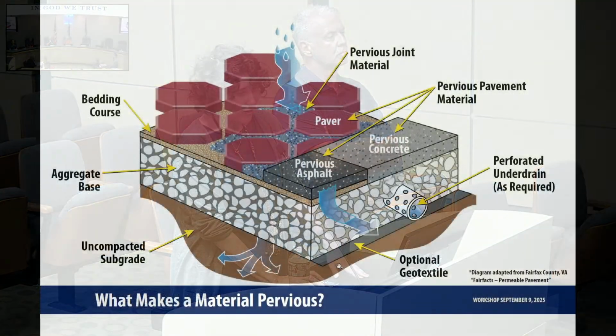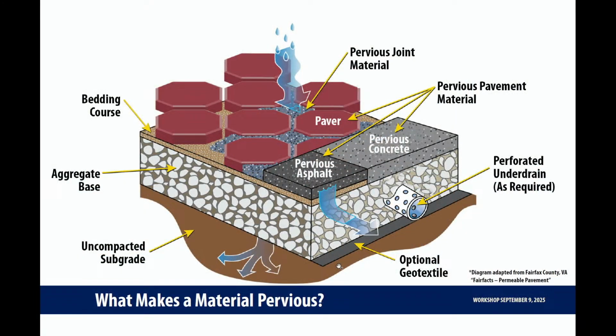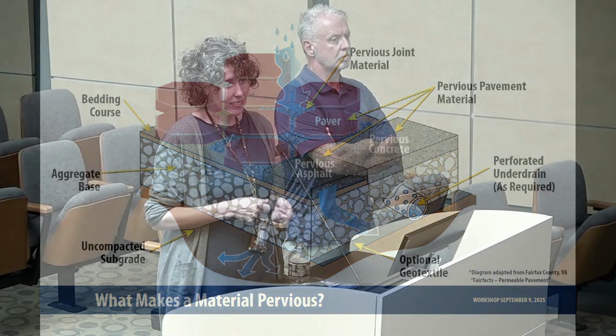Do we have a standard of what's underneath these pavers? All the manufacturers have different standards. There's a variety of cost, and they all look something like this diagram. You'd have a bedding layer for pavers, and then you'd have the aggregate layer underneath it. But it's readily available from the manufacturer as a spec sheet that anybody could upload with their permit application.